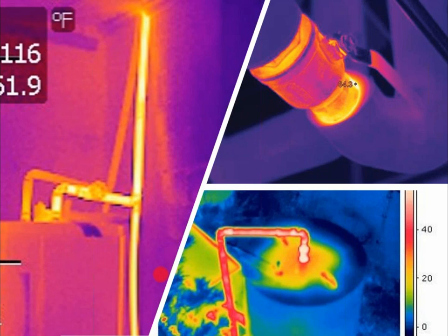But if you take a thermal image, and I'll show you next week, because this lagging webinar is in 2 parts, I'll show you a thermal image of a standing geyser. That clearly shows that heat loss through a standing geyser is significant. All the pipes that come into contact with the geyser itself, there's 3 of them usually. We're not talking about the primary loop or the other ports for the primary loop. You've got a hot water outlet, obviously. You've got a cold water inlet, and you have a TP discharge pipe. Those 3 pipes light up like a Christmas tree when the thing stands overnight.